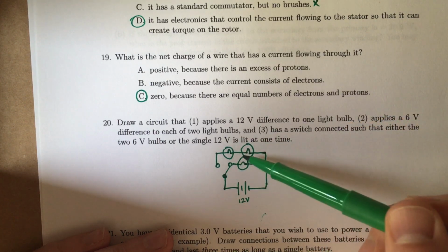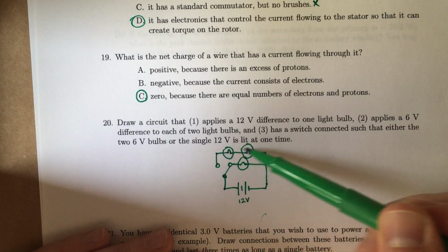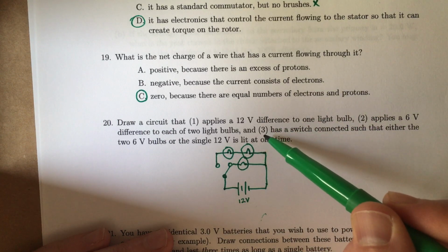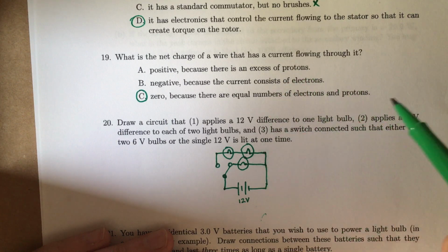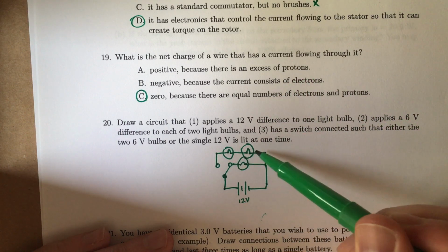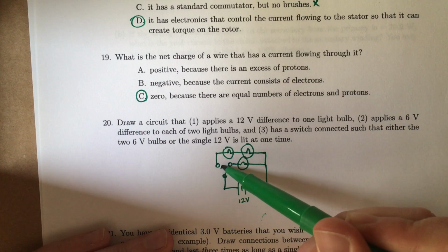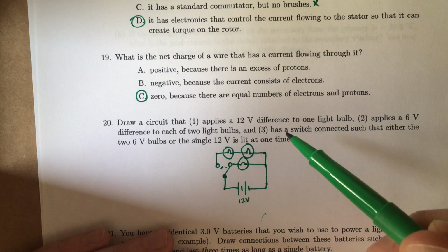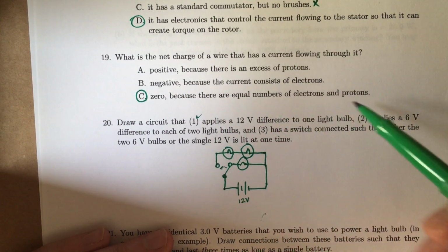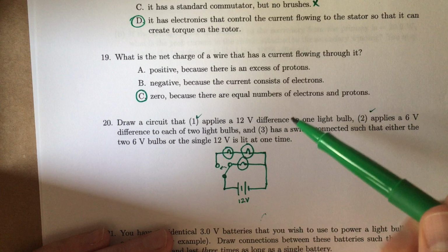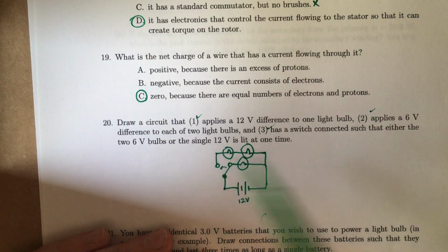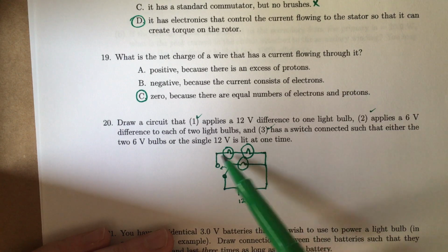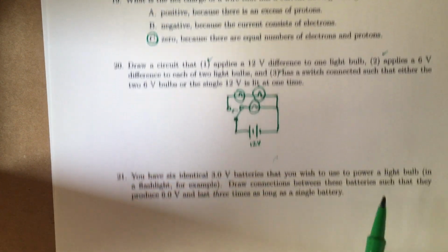In this switch position, there's no completed circuit through those 2 light bulbs, so they won't receive current. And so we're satisfying point number 3 here. And they would each get 6 volts, right? If they're identical light bulbs, then when the switch comes over here, they would split the 12 volts, 6 and 6, and you're done. So 12 volts there, 6 volts to each of 2, and a switch connected so that you can toggle between those 2 configurations. Okay, so 1 bright bulb or 2 dimmer bulbs. All right, and then